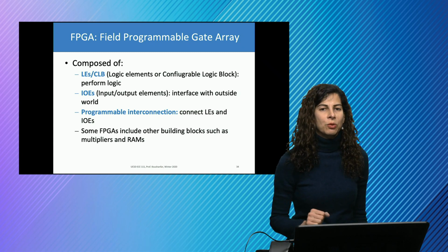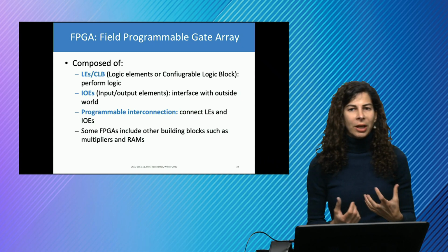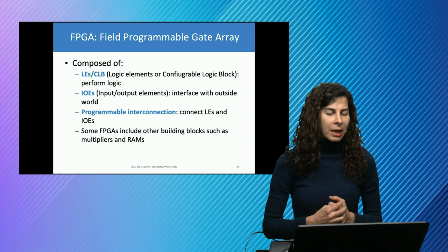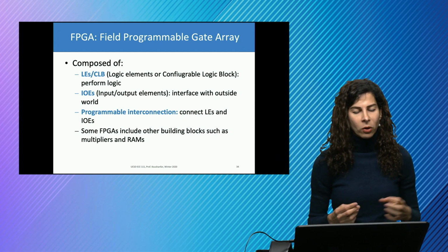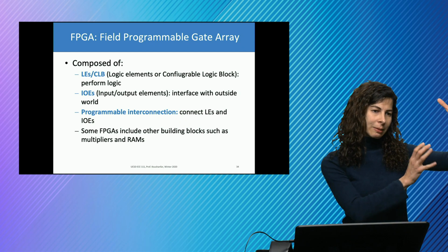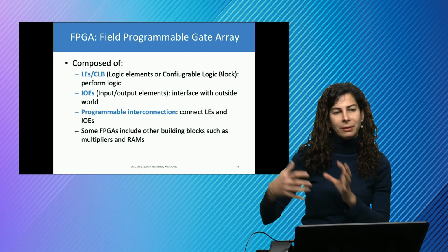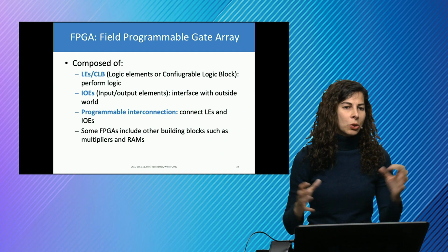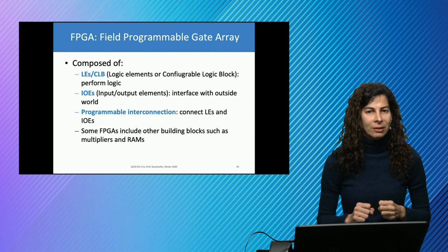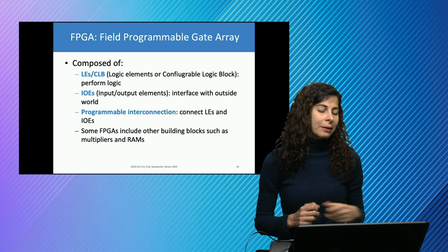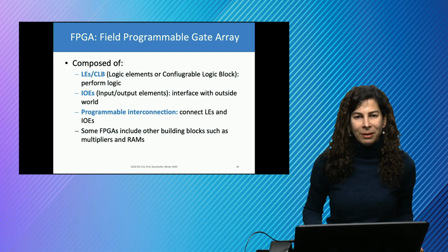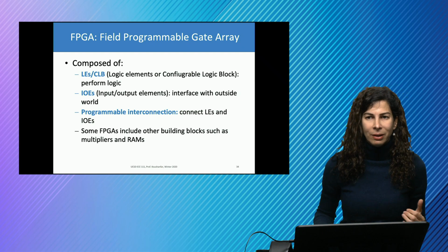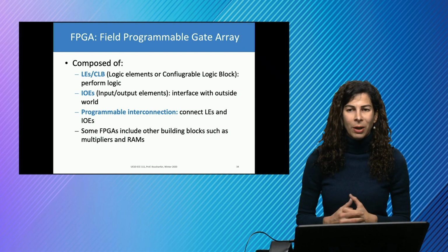What we just saw in terms of multiplexers is a logic element or configurable logic block, but in typical field programmable gate devices, we also have input-output elements that input things to those logic blocks and then output from them. So we go to input-output pins in certain parts of the program, and we also have programmable interconnects. Other building blocks are also possible. Even modern FPGAs may have a hardcore processor or software processor in them.